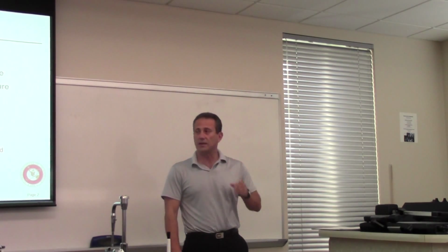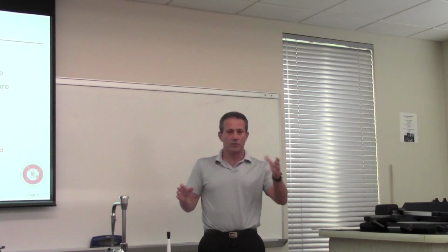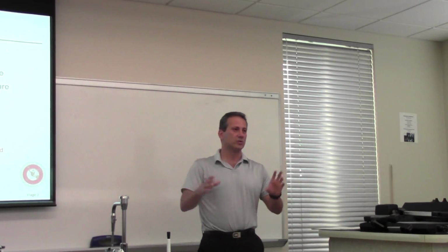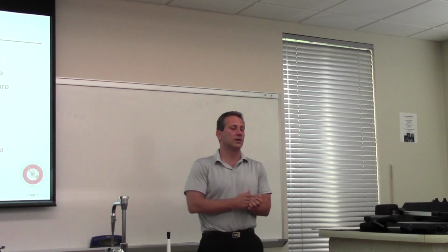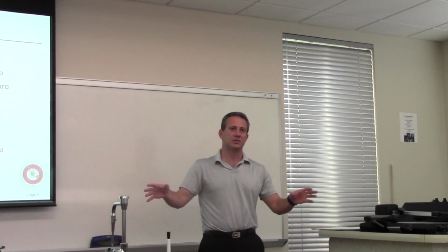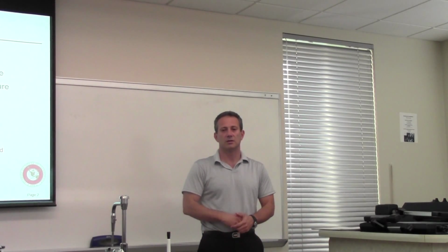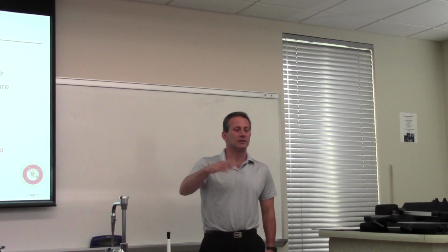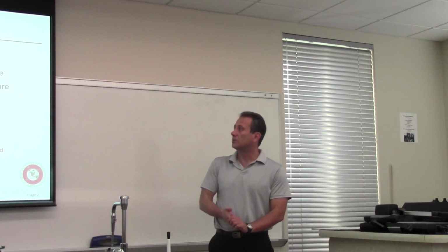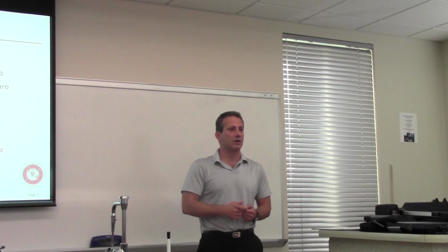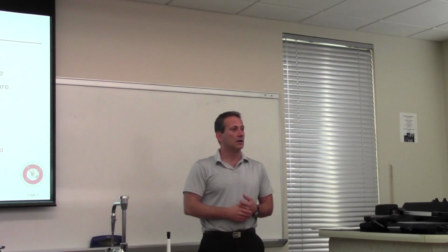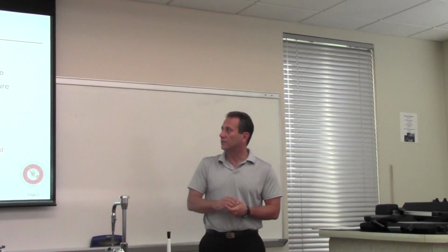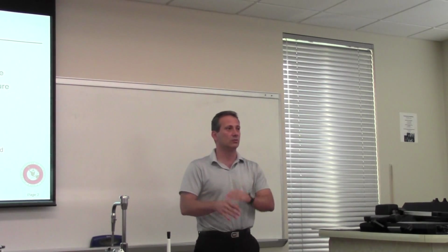Now, when it comes to satellite communication, a lot of you are coming from RF propagation, personal communication systems, where we use mostly noise figure, right? And the reason for that is because all of these are terrestrial systems, and we pretty much work at a temperature range which stays constant, around 300 kelvins, right? Now, in satellite communication systems, the temperature of the background may vary substantially, and therefore it is much more common to use the equivalent noise temperature of a device than to use the noise figure.